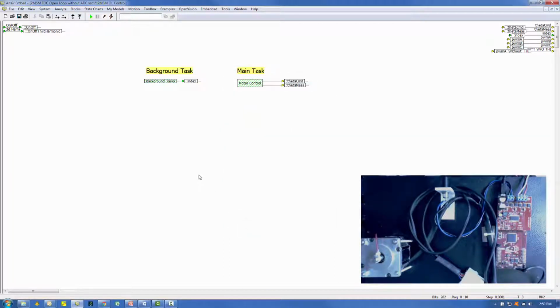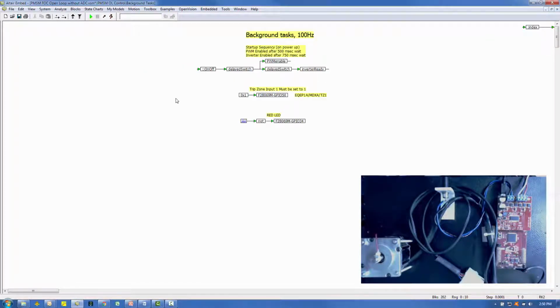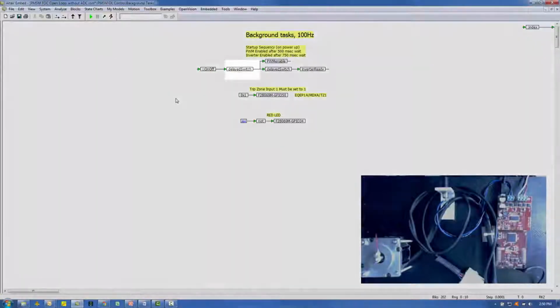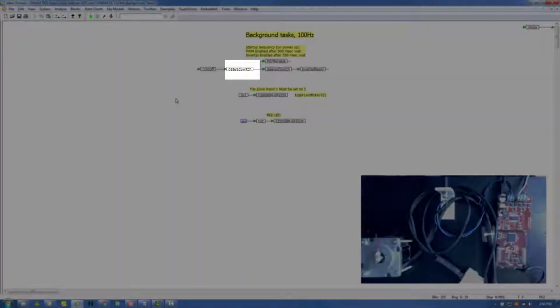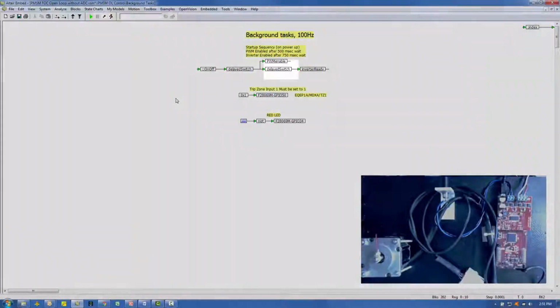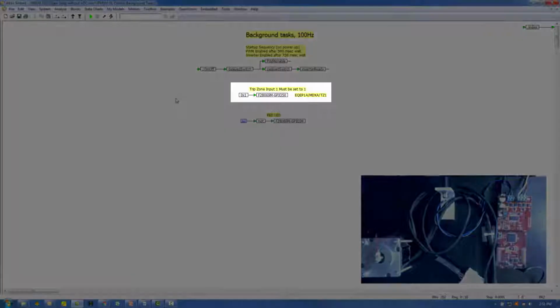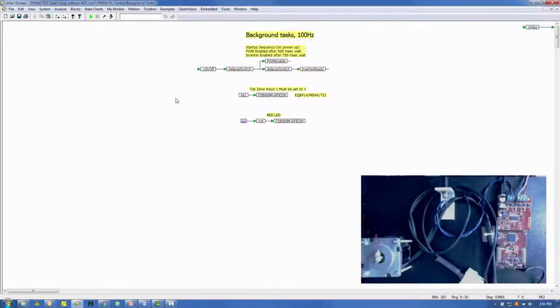rate. Certain timing must occur during startup to prepare the PWMs in the 8301 inverter. Under blocks nonlinear, the delayed switch block allows you to add a delay to the rising and or falling edge of a binary signal. Startup occurs when the on-off signal is selected on. The startup signal is passed through a rising edge delay of half a second before the PWMs are enabled, and an additional 0.25 seconds before the inverter is enabled. Also, the trip zone input 1 is set to 1.